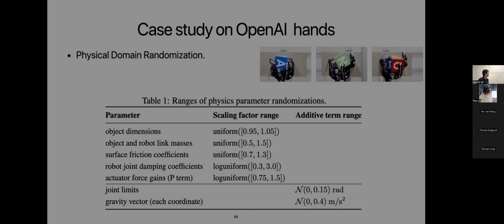Also, there is a limited number of physical parameters you can define in simulation. Although you can define the most important ones, like mass, friction, and center of mass, in the simulator, there are other things, maybe elasticity, that are not quite perfectly reflected in simulation. And there are a lot of unmodeled effects when you consider sim-to-real transfer. So even though they end up using the same robot cube, they still need to do a large amount of domain randomization on the objects.